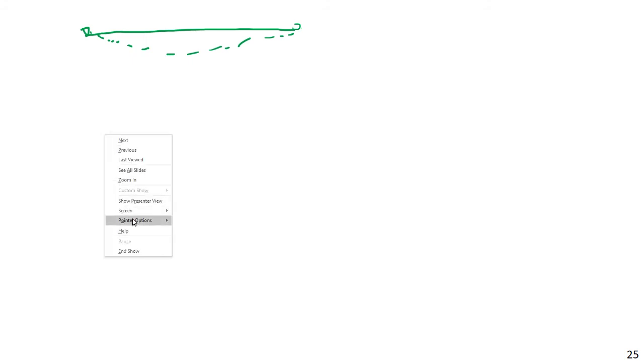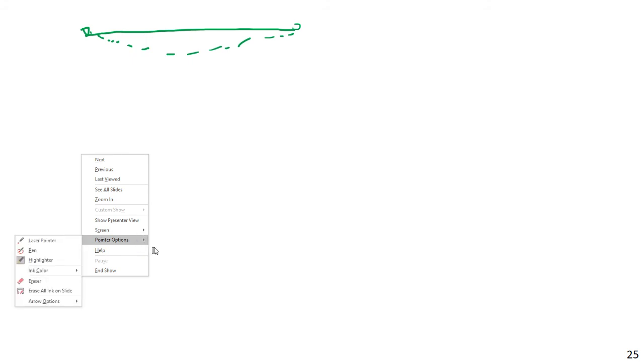If you have a very, very long skinny member and you need to lift it with a crane, if it's too long and thin, it can't even support its own weight without collapsing. It might bend massively under its own weight as you lift it. And also, if it gets too thin, it can be subject to damage as you're moving it around, deploying it, etc.